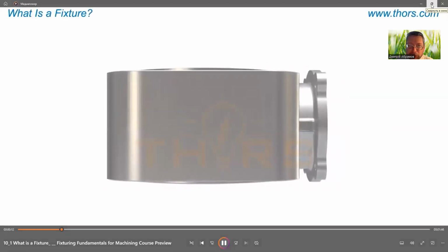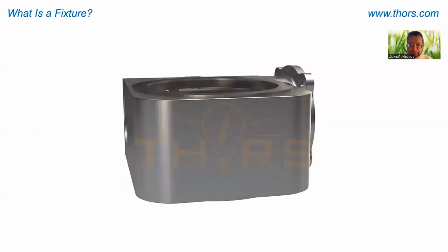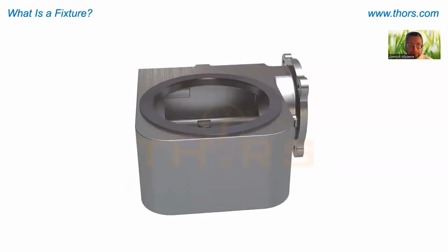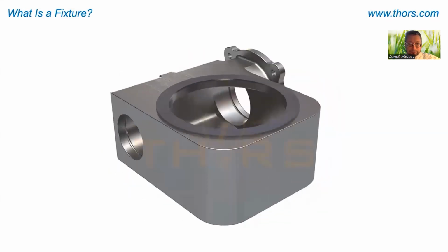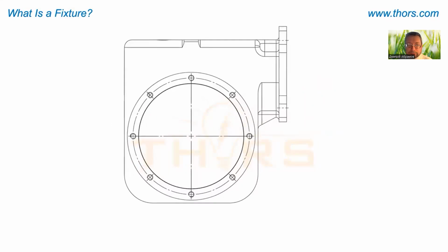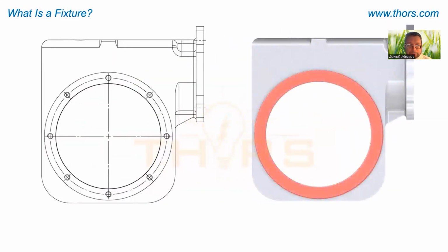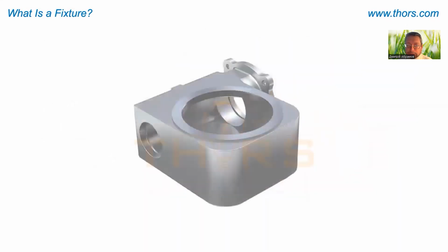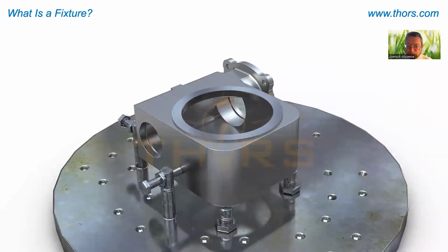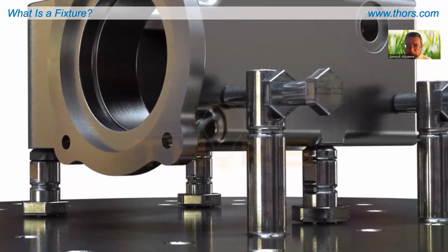Metal parts created by casting, forging, or other metallurgical processes often require machining operations prior to being ready for service. The casting in this example is a housing for a worm wheel gear. The example here specifies that a boring operation will be performed. The part must be secured so that no shifting or movement occurs during machining. The process of securing the part is known as fixturing or work holding.